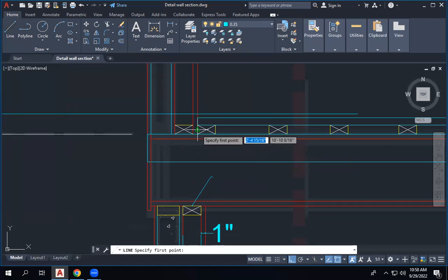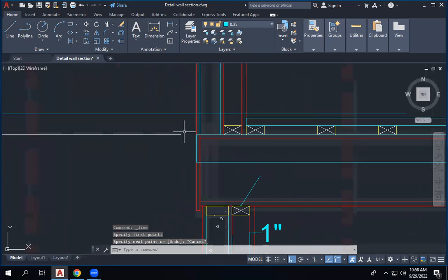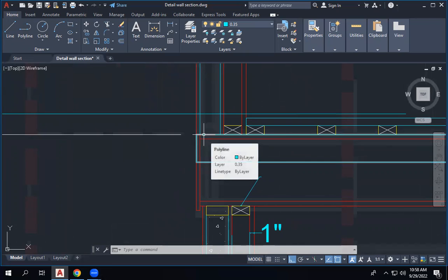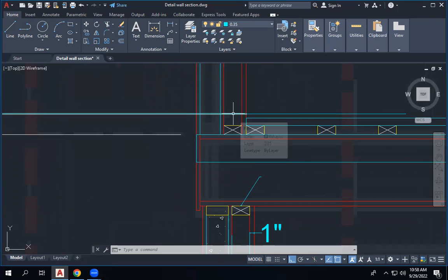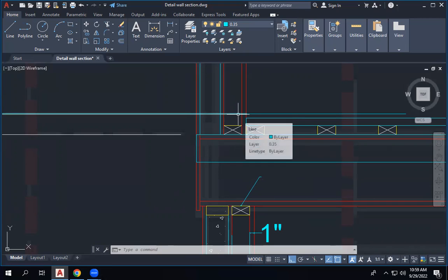here then. It will be like this. Then it's different. Our finished floor level will be 1 inch from his structural floor level. In the office spaces, there is a difference. Most of the office spaces, we keep a height of at least 4 inches or 6 inches from the concrete slab to our finished floor level.